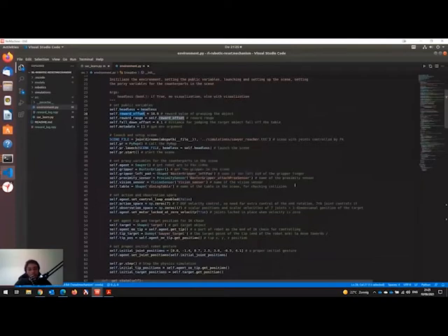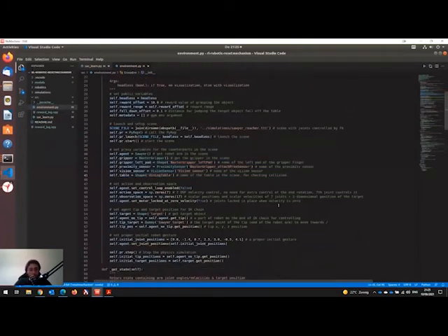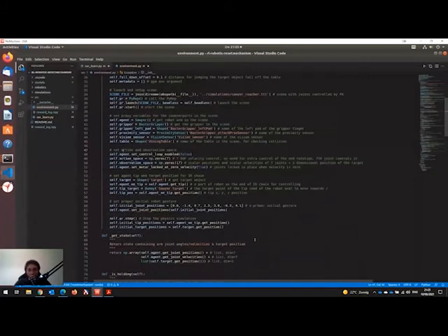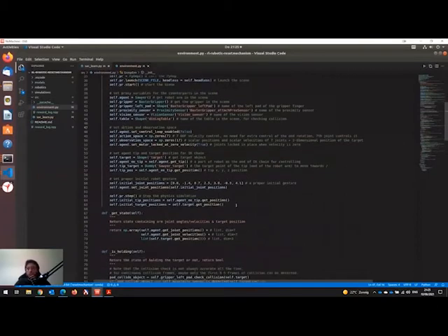Yeah, we detect all the objects in the scene, and we also set the observation and action space. Set the agent tip and target position for the inverse kinematic chain, set a proper initial robot gesture, and step the physics simulation. A step in the physics simulation means just, okay, now start basically.